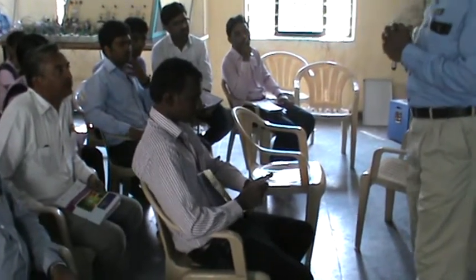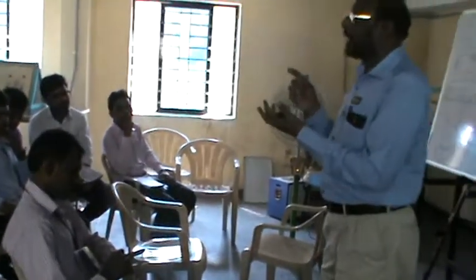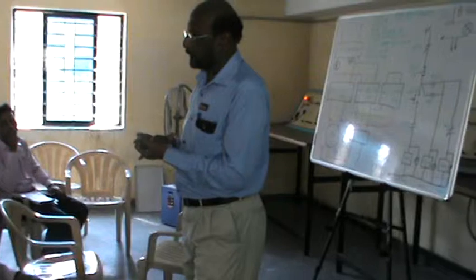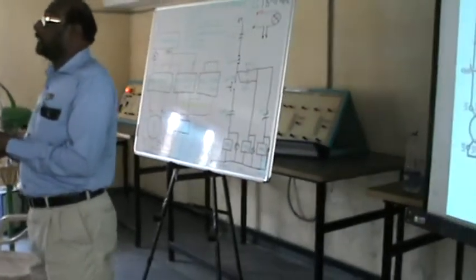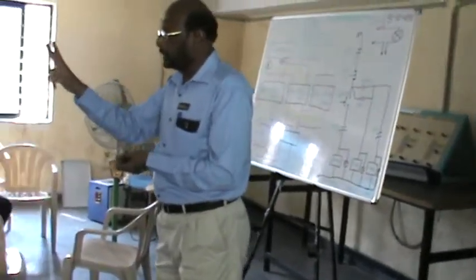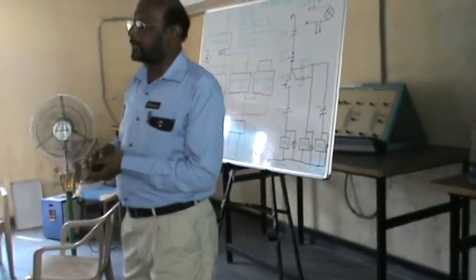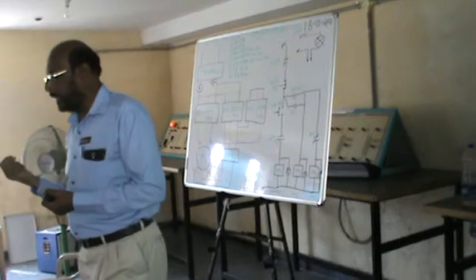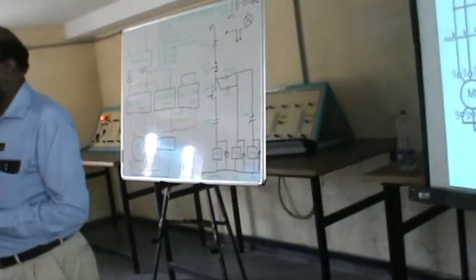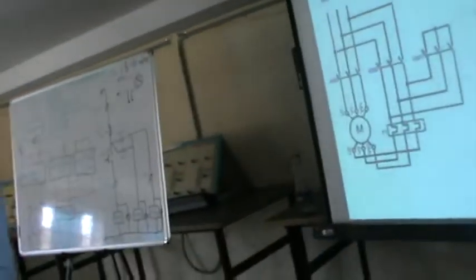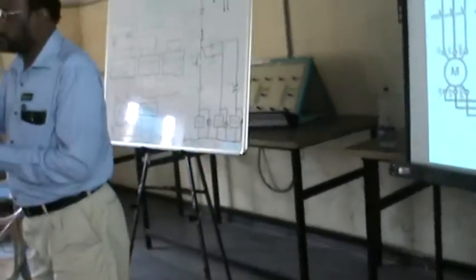Then the slip-ring starter. In the slip-ring starter, we get 3-step, 4-step, 6-step, 8-step, all those. What happens is, in a normal starter we get only 2 steps: one is star, one is delta. In some applications, for example in cement factories, pulp mills, and blowers, we need still smoother current. For that, we go for the slip-ring starter.